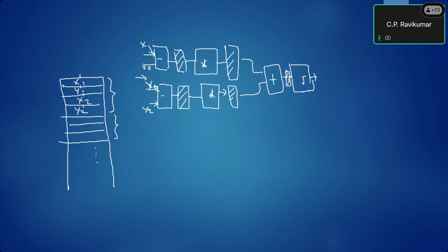Okay? If you use a sequential logic, I mean, if everything is clocked, if you clock everything, then of course the clock acts as a synchronizer, right? Then we are slowing everything down to the slowest stage. Okay, let us say the subtractors take 20 nanoseconds.